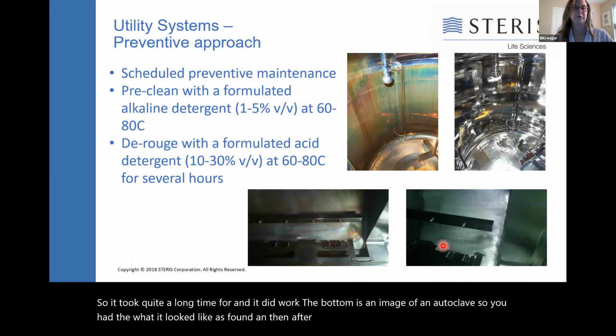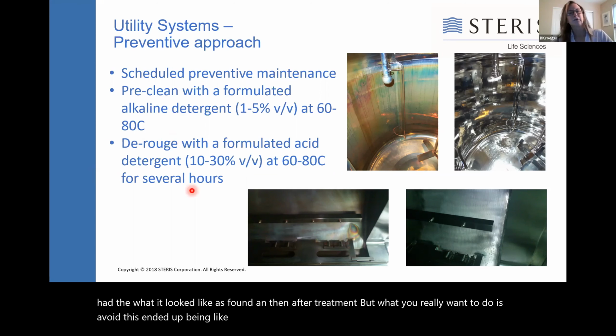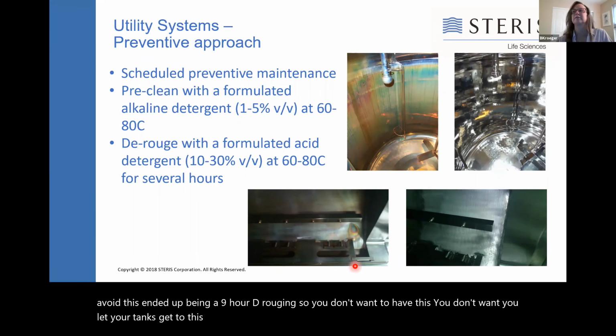But what you really want to do is avoid this. This ended up being like a 9-hour derouging. So you don't want to have this. You don't want to let your tanks get to this level. You don't want to let your autoclaves look like this. So you want to get in front of it. You want to build that data set.